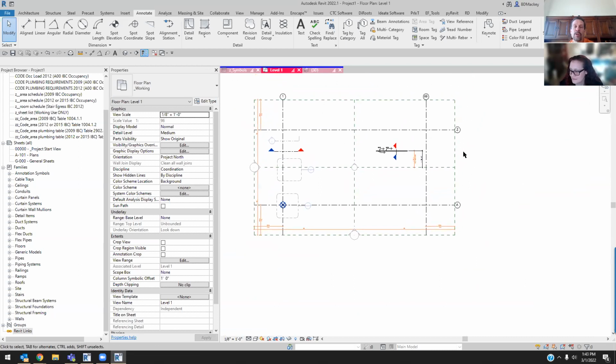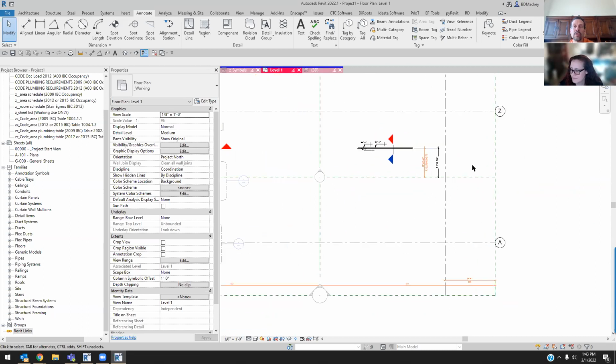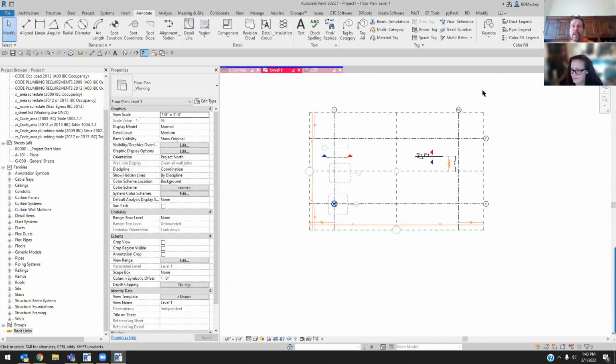And at this point in time, the project was so far along, we're like, what's going on? So that one dimension, we had to set a dimension string up to round to the nearest inch because otherwise it was going to be too far. And thank God it was less than the half of an inch. If it would have been 0.000001 over half of an inch, Revit would have rounded it up to be 22,000 feet, 1 inch, not just that. So it was ridiculous what it was.